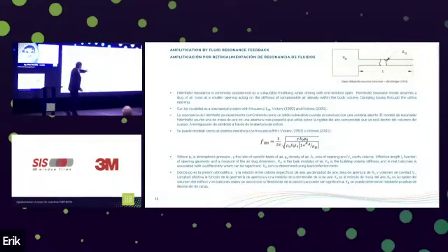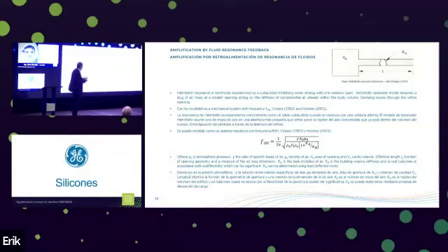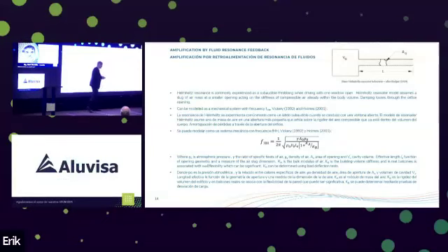Now, Vickery and Holmes have derived a formula for the Helmholtz resonance. I won't go through all the variables, but key are Ka and Kb. Ka is the bulk modulus of the air, and Kb is the building volume stiffness. Now, this is important because in real buildings, the stiffness can often be associated with the facade. So you might have, say, balcony doors, and they can flex, and they can actually affect this Kb value in the Helmholtz frequency.